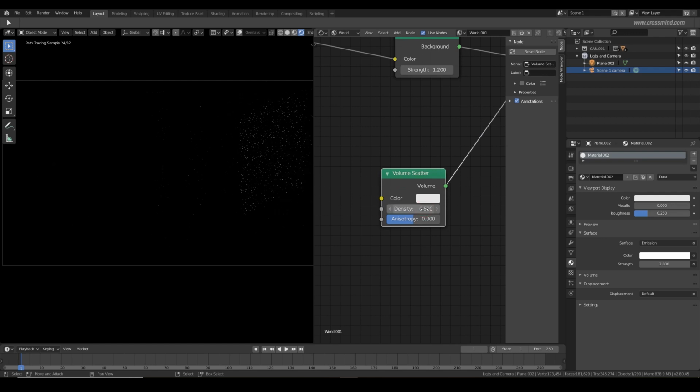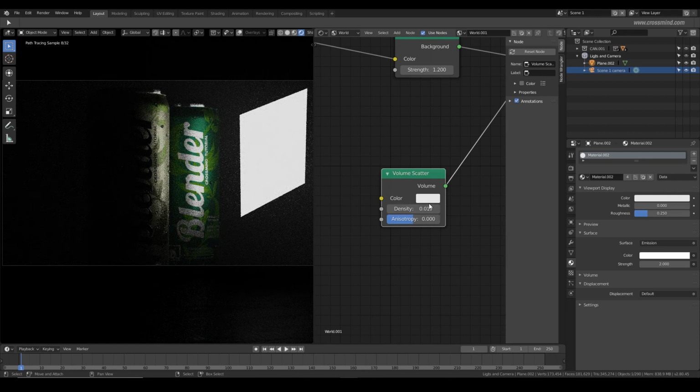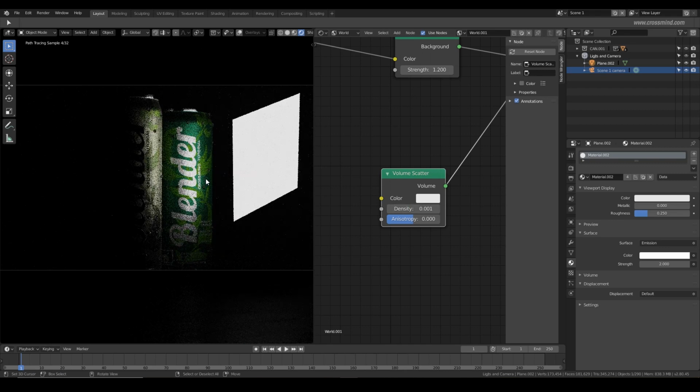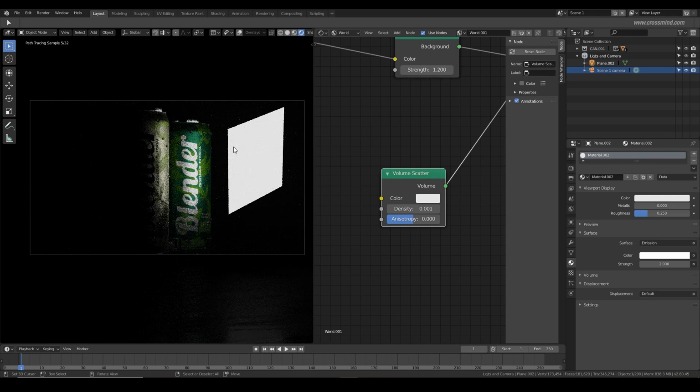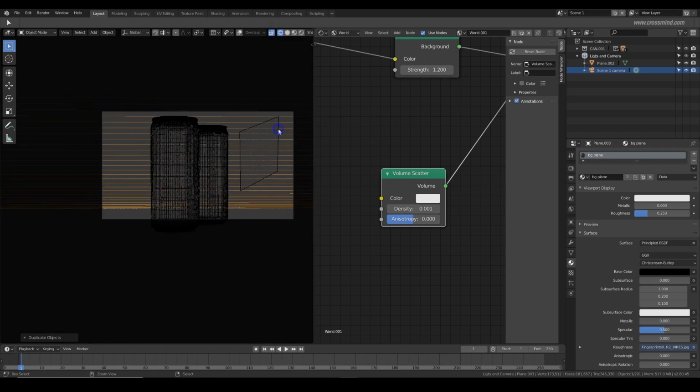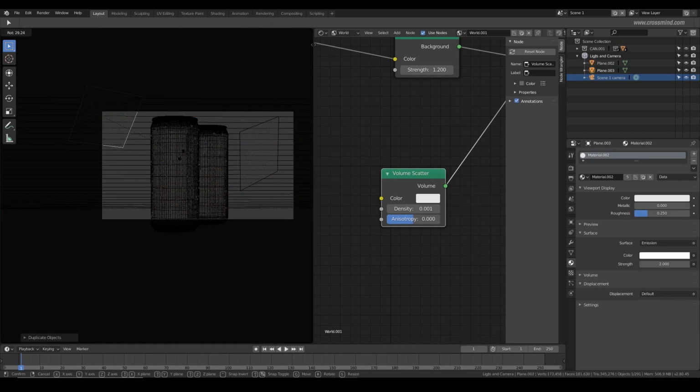All that stuff in the room or in the air receives the lights, and the interaction is much more natural. It looks photorealistic. So yeah, density, we definitely need to keep the density very low, else it's going to make the scene very dark and foggy. So I used 0.001.